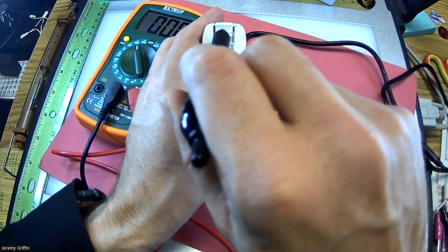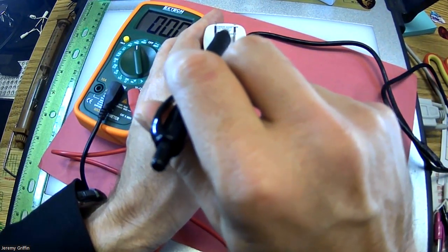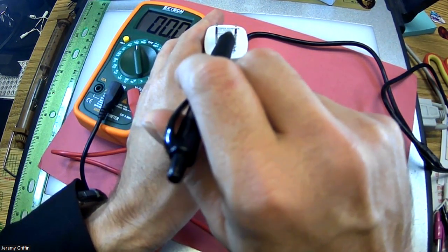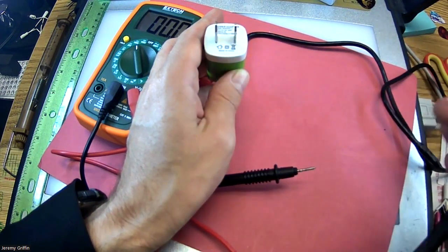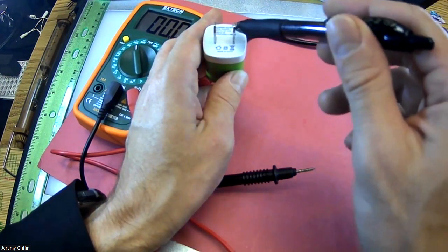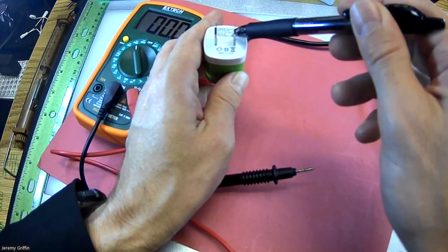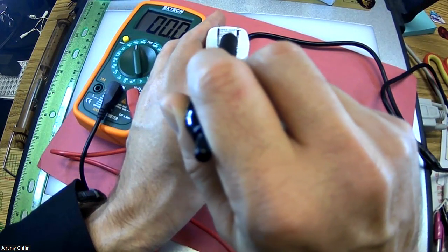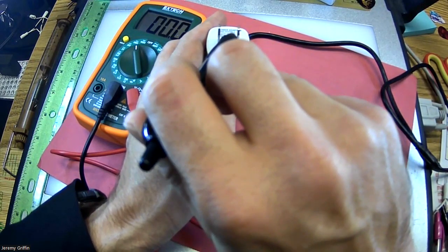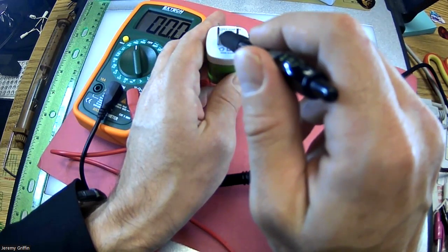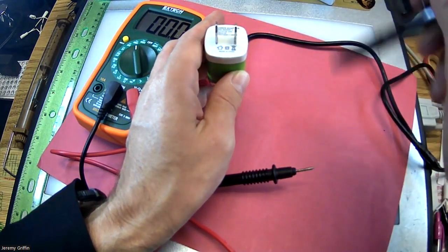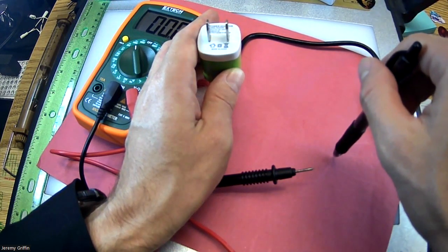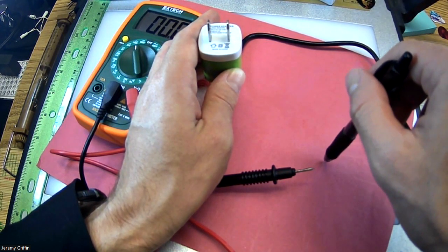You guys see where it says input alternating current goes anywhere from 100 to 240 volts. Well, that should cover all the main world standards, right? Anywhere in North America, you're at about 120 volts, plus or minus a little bit. The European standard, like if you go on vacation in England, is 240 volts. So 120 in the United States, 240 over in England. What about the frequency? Remember, alternating current oscillates back and forth with some frequency. Do you guys remember what the American frequency standard is?